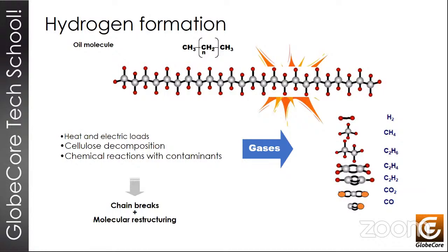There are two processes of gas emission in the transformer. If the gas produced contains hydrogen and hydrocarbons, this indicates the breaking of the carbon-hydrogen bonds of the oil by electrical discharges, and this process is known as gasification. If the released gas does not contain decomposition products, then this process is known as dissolved gas emission. And both forms of gas emission are very important in high voltage electrical equipment.